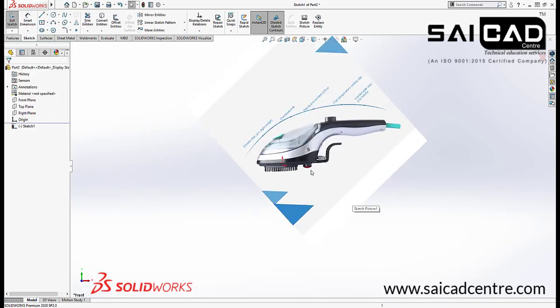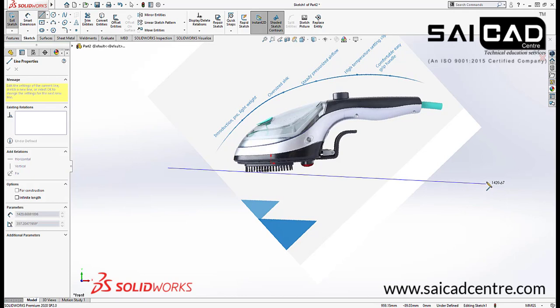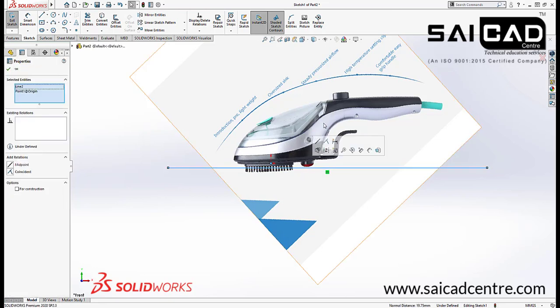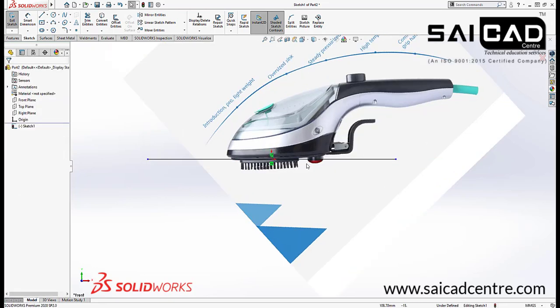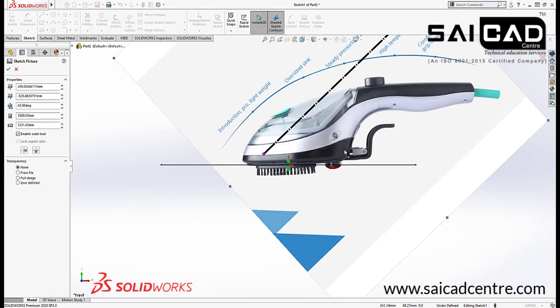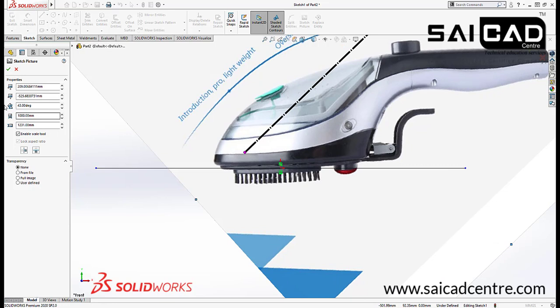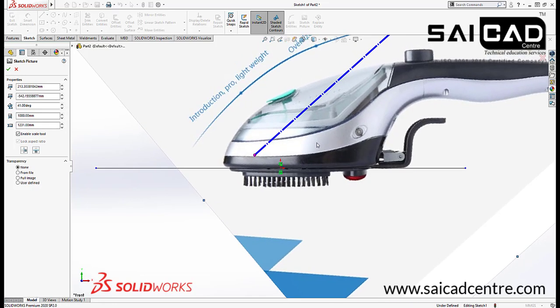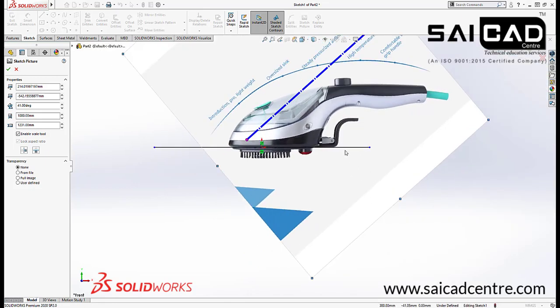I just want a line, just create a line. You can see we have a relation, and this line is horizontal, so I will just use a relation for midpoint. So I have a reference here. Now I want to rotate it, so just double click and the modification option will be there. So I want to rotate it somewhere like that, and I can just move it. So you can see we got the face almost flat down there. So this was the shape.